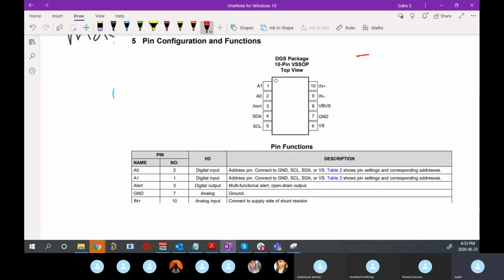This is an INA226. So it's a little current sensor that we use on the VCU to measure how much current is coming in from the 12-volt rail. And you can see here SDA and SCL. So these 2 pins would go to the VCU and you measure there. Make sure you have the common ground. Same as VCU. If you guys don't have a common ground, you won't be able to talk.